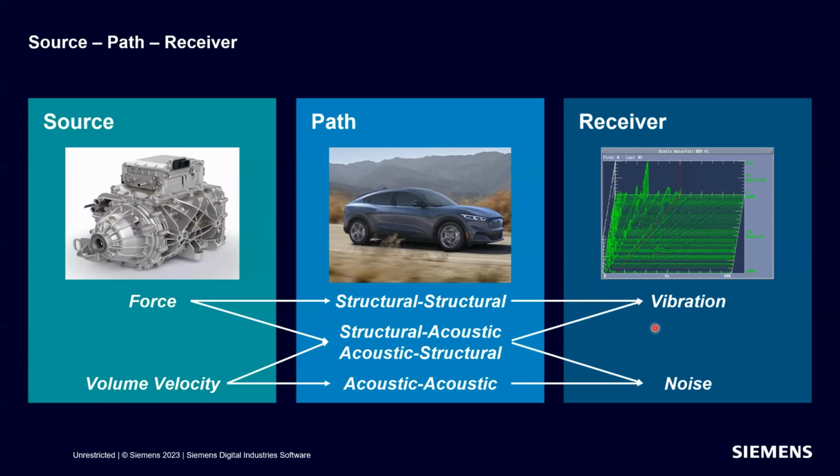And then we have our receiver locations, and between where the forces come out of the source and to where we experience things as a receiver, we're going to have things like FRFs to quantify this. So we'd have operational forces here, some sort of FRF that might take a mechanical force input and tell us how much force we get out at the steering wheel in this car, for example. Or it might go here, force in structurally, and then comes out acoustic at the operator ear.